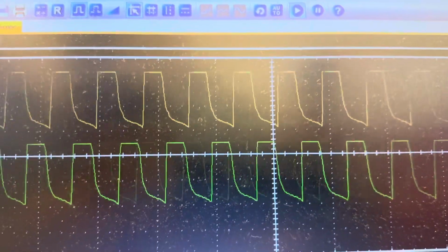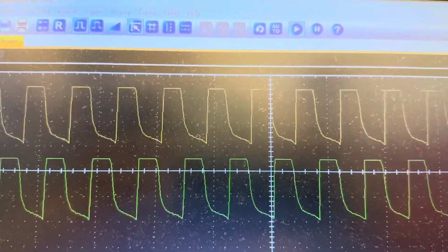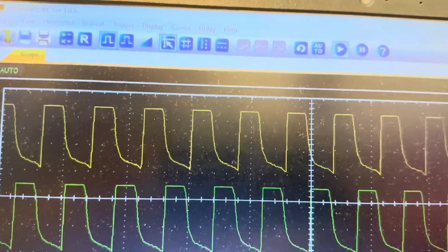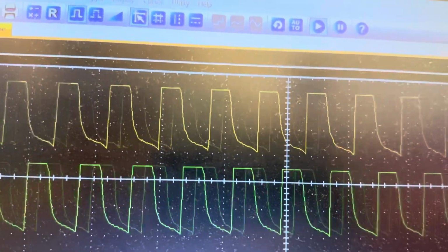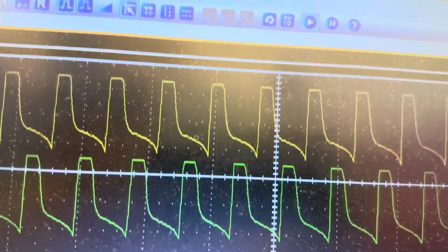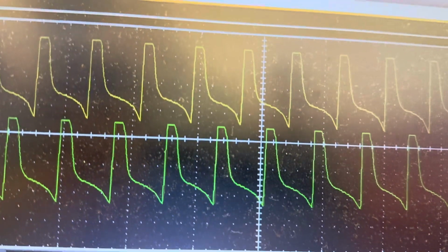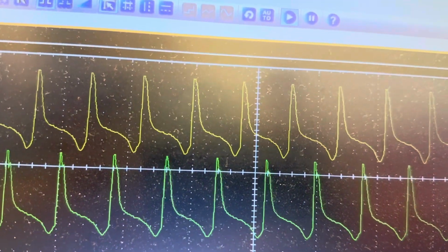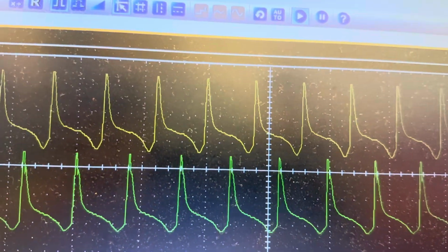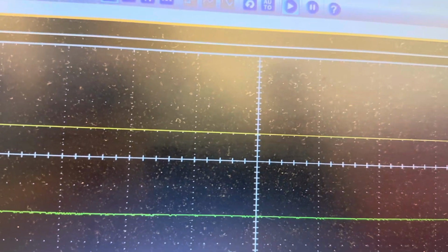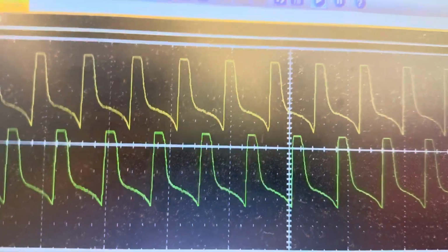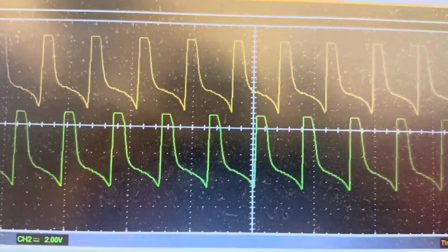I am further reducing the voltage. The circuit is still maintaining 208 volts AC and this is the waveform. You can see the time period of the waveform has increased. Now if the voltage increases, you can see the time period will reduce. You can see this is the maximum possible PWM and the voltage at this point is 247 volts AC. If I further increase, the circuit will shut down. So like this, the PWM function is working for IC TL494.